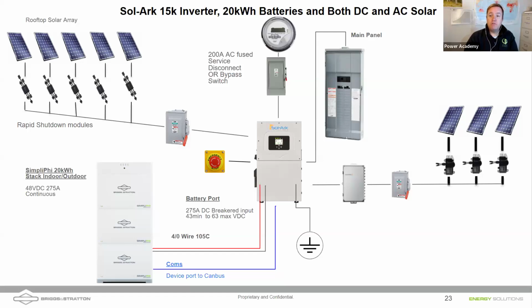You do notice that we not only have the AC coupled solar on the right, but we additionally are able to add DC coupled solar. We can bring in both. So perhaps the system that was out there, they got some old AC coupled panels on the roof. They're adding an EV. They're adding heat pumps. We can then add additional solar and bring it in through that DC charge controllers as well.